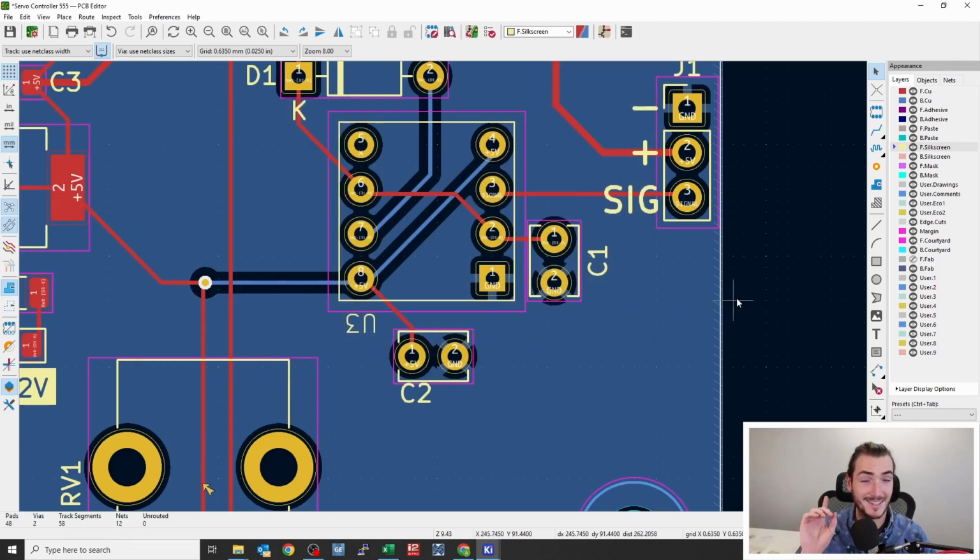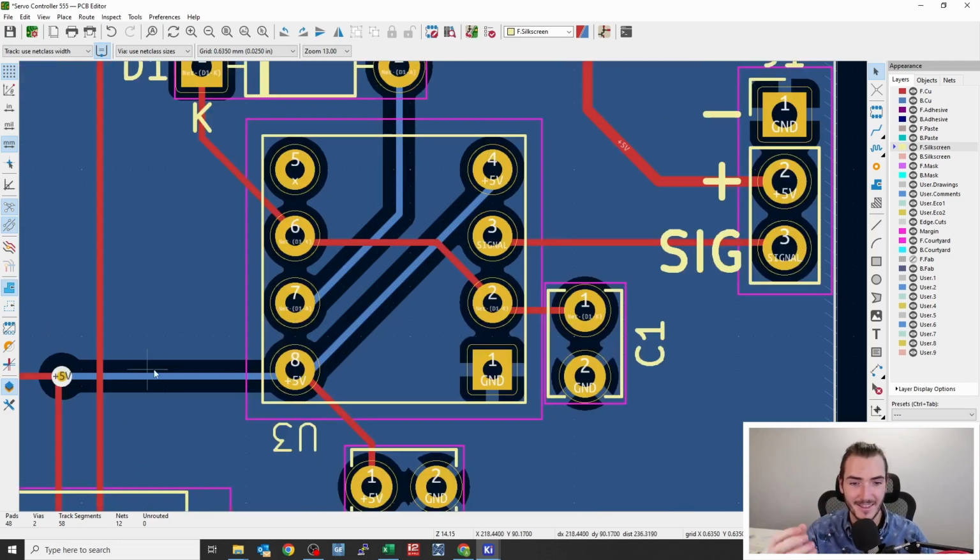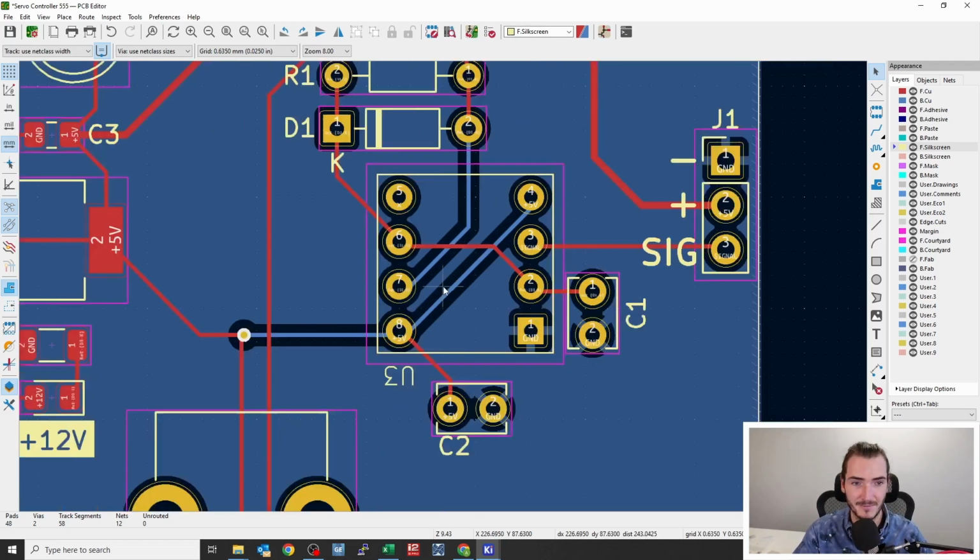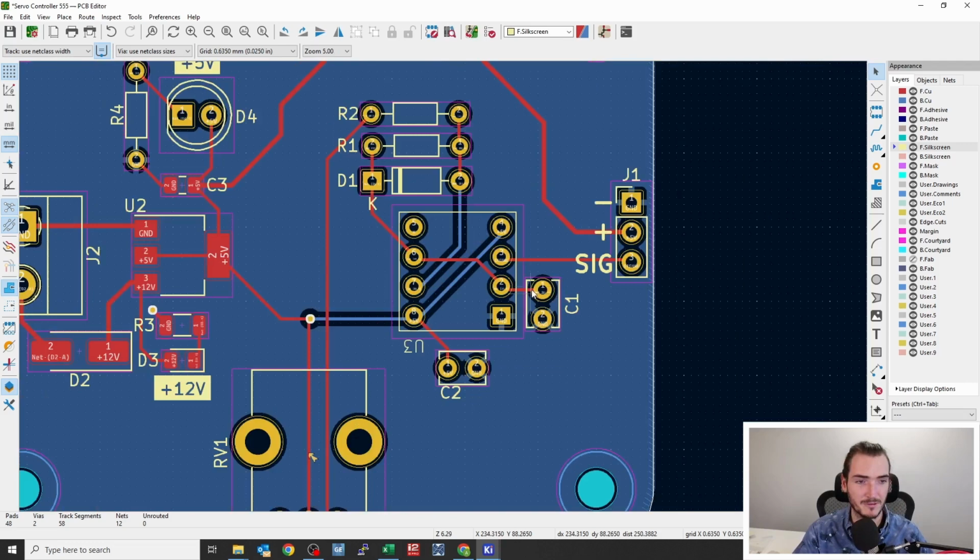But that means that we made a symbol from scratch, we made a footprint from scratch, and we verified that it worked against an existing one because I've just dropped it into a PCB design that has all the traces routed, which means that all the connections are made. We would have had heaps of errors if we'd made a mistake because there would be a trace going to a pad that is not intended. So we got that one-to-one relationship.